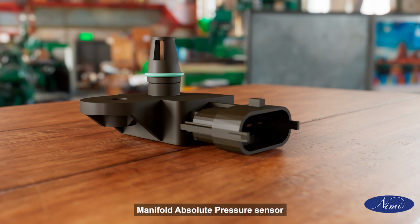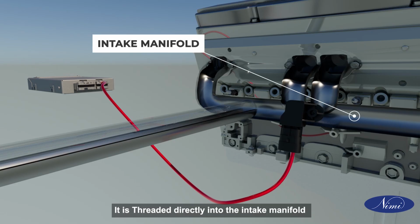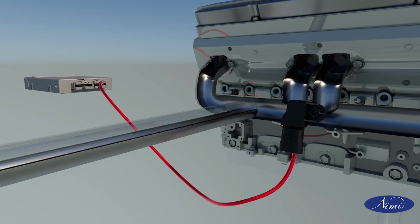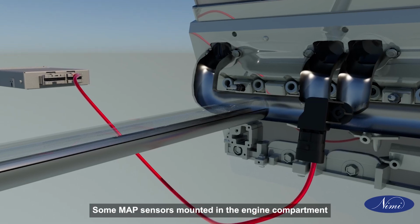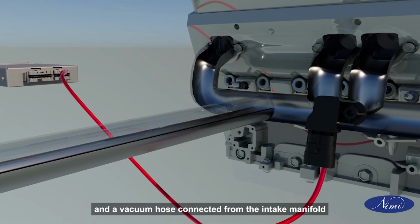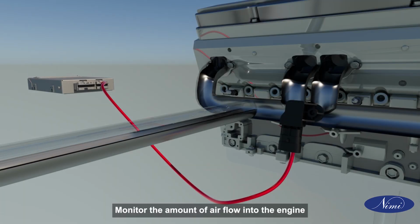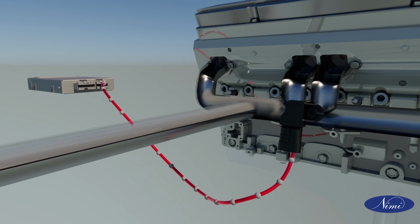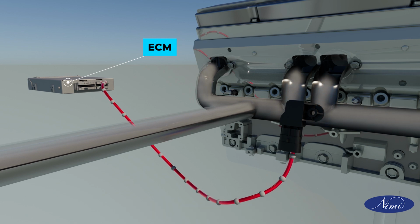Manifold absolute pressure sensor. It is also called the MAP sensor. It is threaded directly into the intake manifold. Some MAP sensors are mounted in the engine compartment with a vacuum hose connected from the intake manifold. It monitors the amount of airflow into the engine. Based on this, the ECM calculates air density.